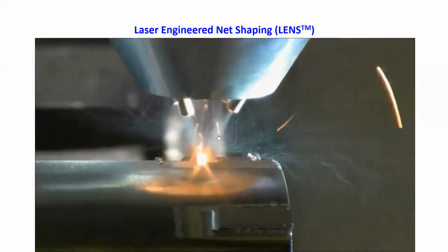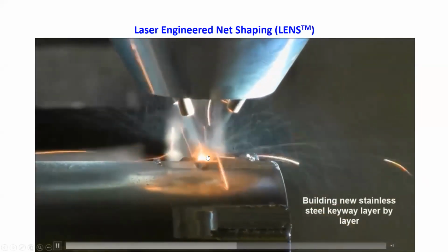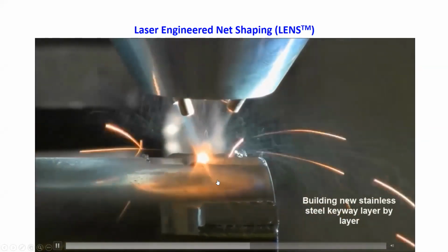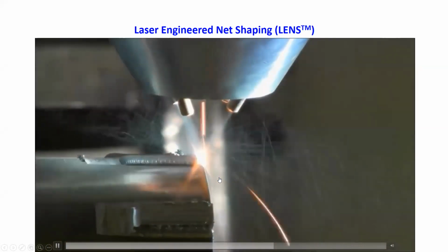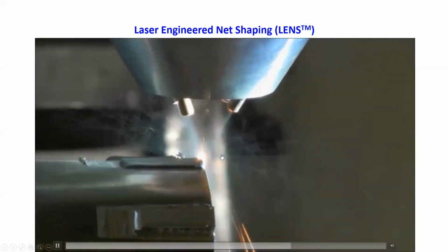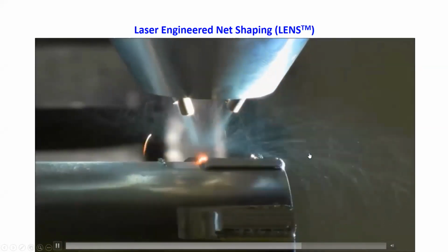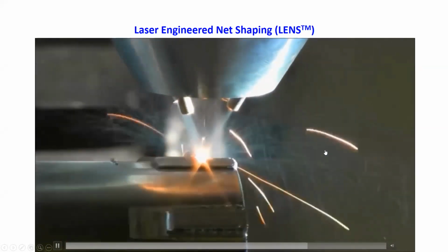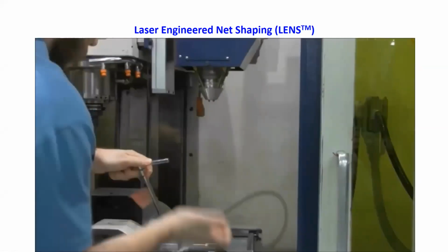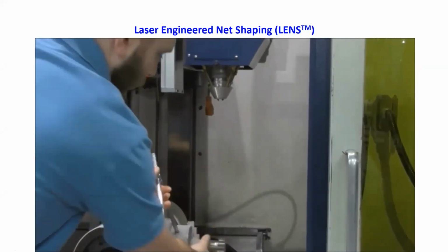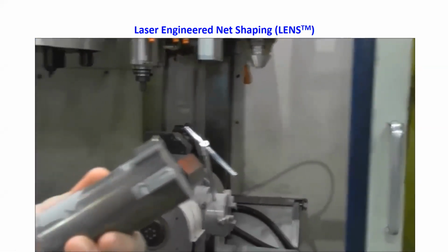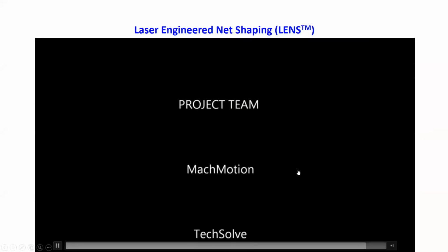You can see that we have the laser, we have the two powder feeders, and these are scanning along some particular direction, to and fro or back and forth. Once we complete one layer, usually this is shifted by 90 degrees, and the next layer is formed on this 90 degree turning, so that we can have an even microstructure at the end of the process. So every alternate layer we are changing the direction, and depending on the final requirement we can set different parameters. Once this is done, the part is simply removed and can be used.